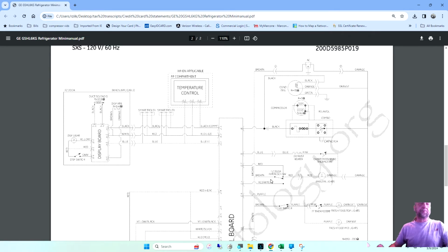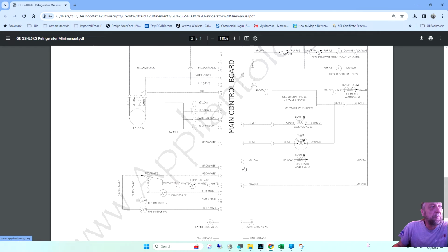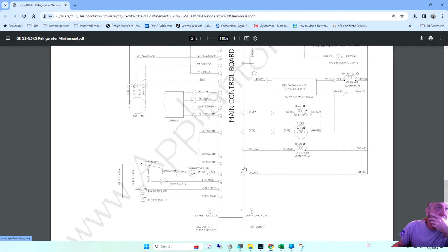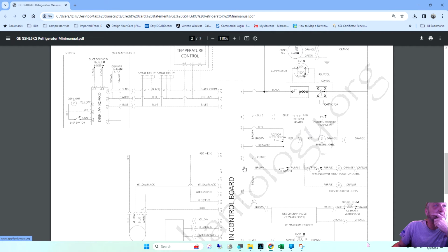Well, guess what? I replaced the board. And the day I replaced the board, because I also have experience with that board, whereby when you unplug it and plug it back in, the board dies, I was hoping that it wouldn't happen when I installed the new board. So I installed a new board, and the compressor wouldn't run. So I thought, okay, maybe it's a delay, and then it started running, right? I can hear the evaporator.